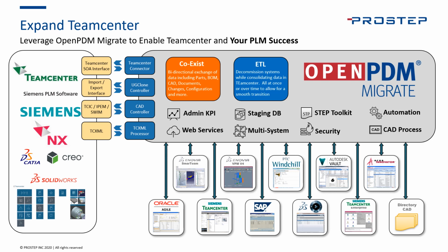We also have at the bottom, specifically for OpenPDM Migrate, a TCXML processor. This is to execute low-level TCXML processes for importing data from your staging database. This is generally the highest performance integration point or API for migration into Teamcenter. But it's sometimes challenging to get data in the right formats, or it may not be supported, like in the case of third-party CAD.